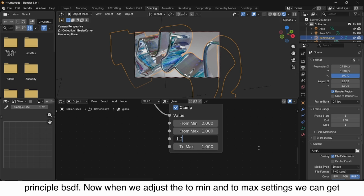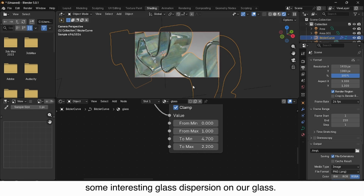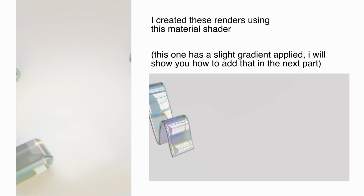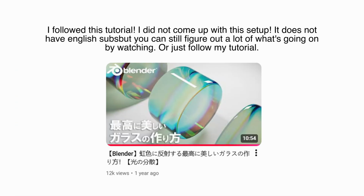Now when we adjust the 2 min and 2 max settings, we can get some interesting glass dispersion on our glass. The closer these values are to 1.5, the more realistic the material will look, but you don't have to keep it completely realistic. I created these renders using this material shader, and I followed this Japanese tutorial to achieve this effect.